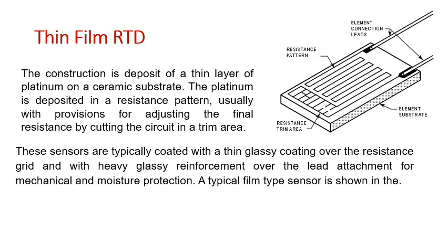In the thin film RTD, the sensitive material is made of platinum, and the platinum is deposited on a certain element, as you see here. So here is the sensitive material, which is platinum, as I said, deposited here. We keep space for the resistance trim area.